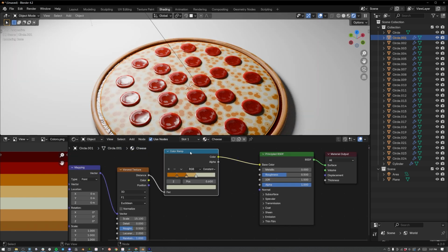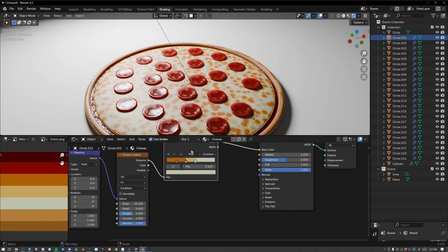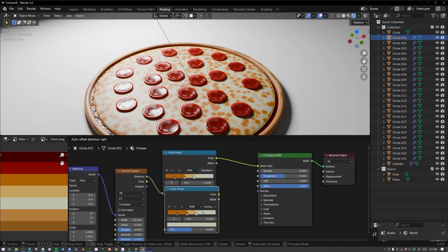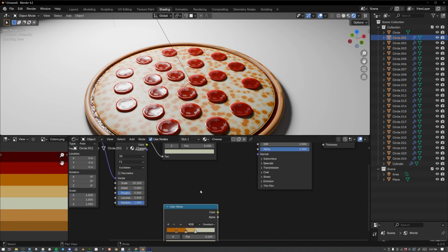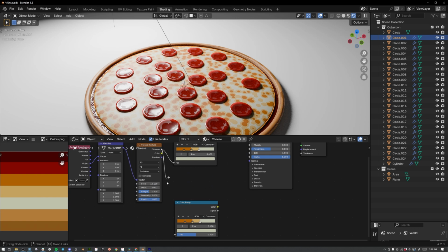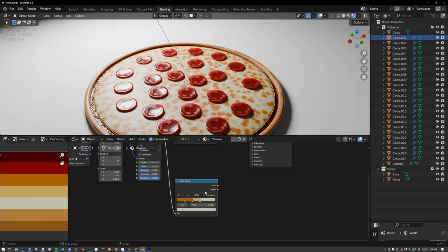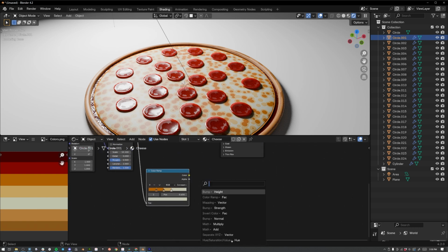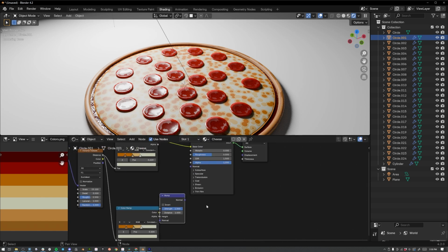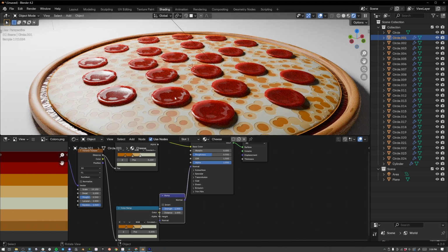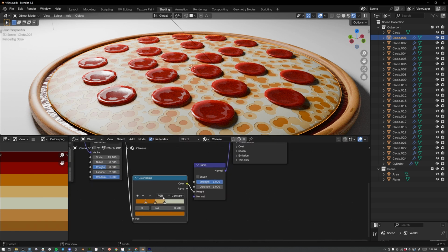So now we need to create what's called a bump map. I'm going to select this, Shift and D, duplicate it and move it down. And then let's go ahead and drag this distance node into the factor of this color ramp. Go out of here into what's called a bump node again. Go down to height, select enter. We're going to click and drag from that normal up to this normal, and now you can see that we're affecting the height. Let's change this to black and white color.